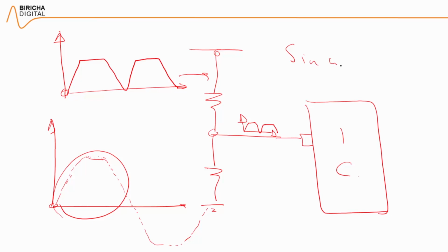In digital, you create a sine wave really quite easily. All you have to do is you say sine omega t is equal to A. And therefore it lends itself much better to creating a sine wave. Of course, there are headaches associated with this. In particular, if the line goes down or you have a brownout, then the value of this sine wave that you're generating in your digital system might be wrong, and therefore you need to look after that sort of thing.